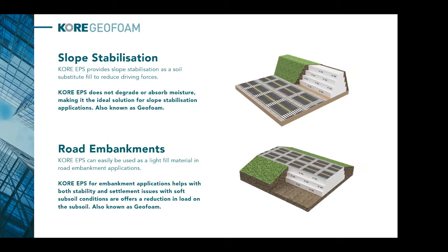Again, these would a lot of the time be referred to as void formers as well, but we're starting to refer to them more as geofoam. So it's basically an EPS material used in connection with civil projects, or whatever it may be that's involved with being used under the ground, under soil. And here are some examples of it. One particular use could be slope stabilization, and we've seen some projects over the last few years with EPS being used there.